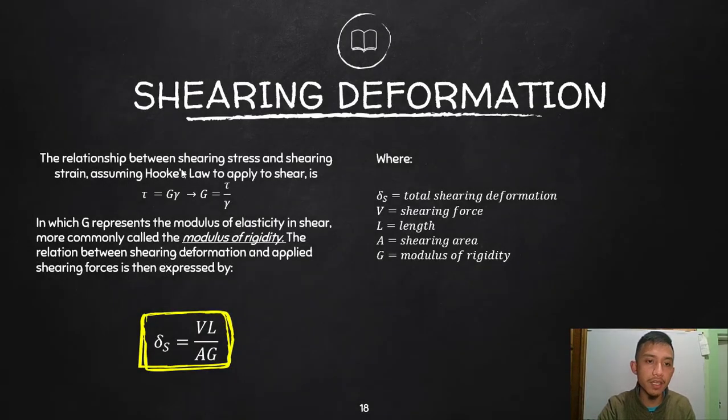For shearing deformation, we will be using the shear stress, which, by the way, we did not discuss before. But the same as your Young's modulus, we have what we call the modulus of rigidity, which relates the shear stress with your shear deformation, your gamma, the shear strain. So playing around with this, your G is the ratio of the shear stress to your shear strain, gamma.